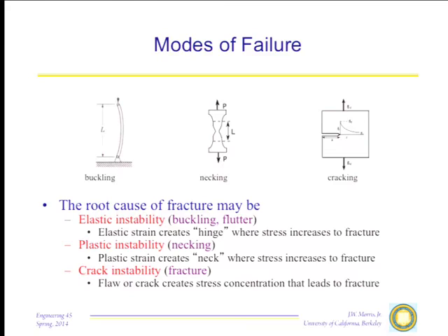You may not know it's there. You put a load on the material. The load may be well below the yield strength of the material, but that load is intensified at the tip of the crack, as we'll discuss in just a few minutes. And because of that intensification of the stress, you may create a situation in which that crack goes unstable, propagates through the material, and bang, you've broken it.